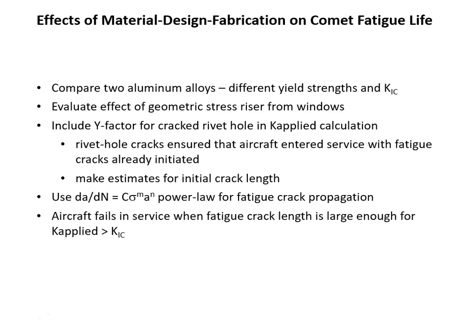So just looking at, again, the de Havilland retrospective as kind of a little lesson in design. This is an exercise that we can do with a spreadsheet. Fortunately, I will not go over that in this lecture, but it's possible this might be a homework assignment. But you can basically take the conditions under which the de Havilland was designed and used, and you can actually use modern values for K1C, and you can compare different aluminum alloys.